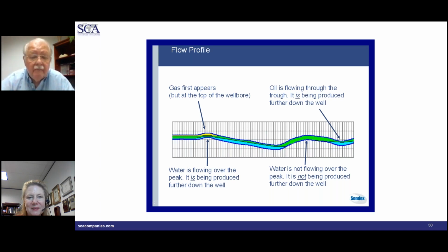For example, if you have a standing pipe and you have bubbles going up, the volume of water, if you were to flash freeze it, would be about, let's just say 80% water, 20% oil. That would be a measure of the holdup, how much is present. It's a snapshot, it's not a dynamic thing. But if you looked at the flow, the bubbles would be propagating up through the water at about 30 feet per minute relative to the water. So you would have a lot more oil. You would have much more than 20% oil coming out. You might have 60% oil cut, 40% water cut. But the holdup would be 80% water and 20% oil. And the reason is that one phase is migrating up relative to the other.